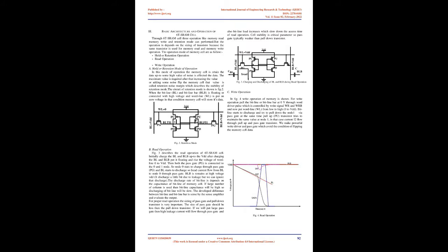To overcome the instability of memory we design some write and read assist techniques through which we can work at low supply voltage without impacting the performance of the memory cell. For low leakage we generally use multiple threshold transistors, decrease the rail-to-rail swing of the memory cell, and use a dual power supply, through which we can reduce the standby mode current and leakage power dissipation in the 6T SRAM cell.